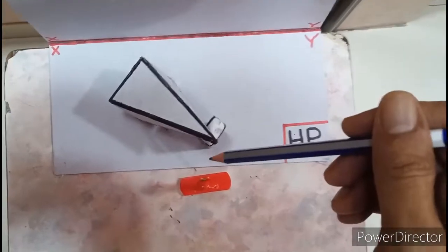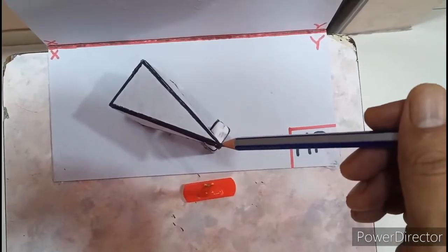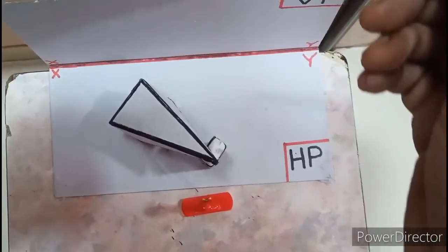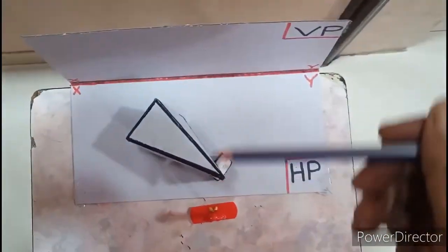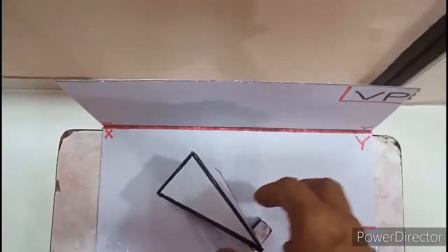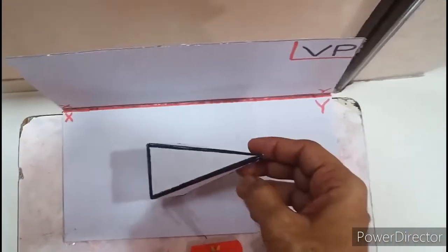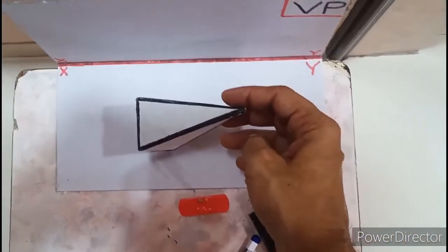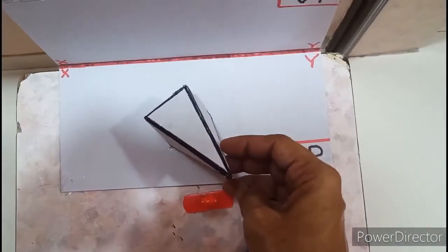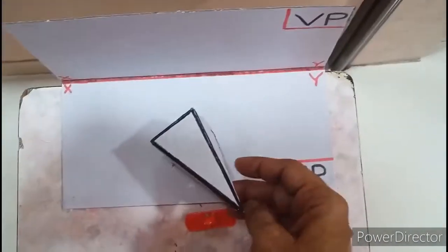So in the exam they can twist the question. They can say that instead of apex near to the observer, it is away from VP. So in top view it is away from VP. Initially the pyramid was like this. If you want the apex near to the observer, you have to turn it like this, right? See, the apex is now near, but it has become away from VP.